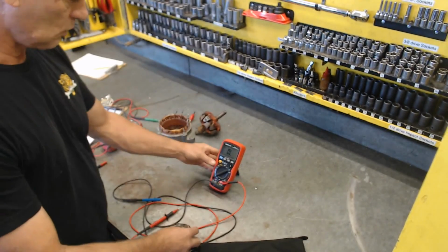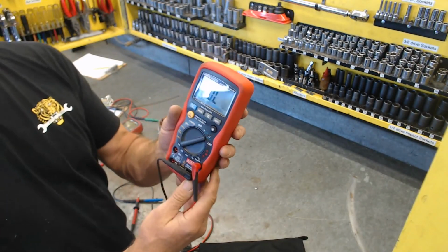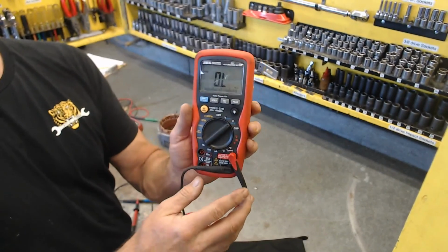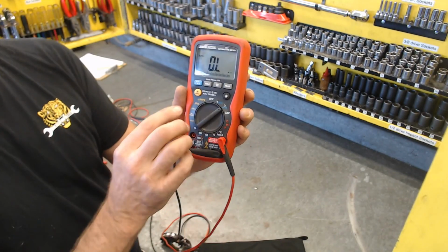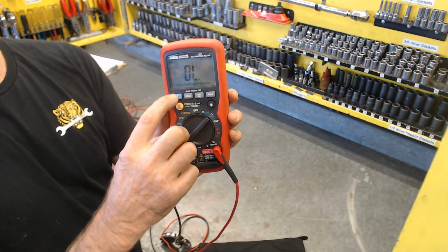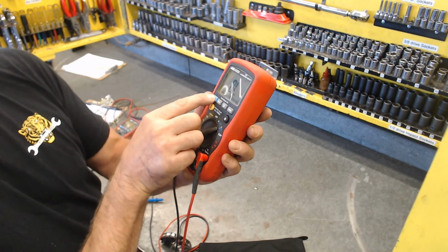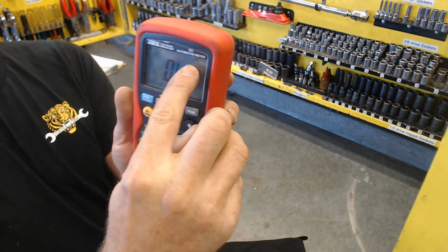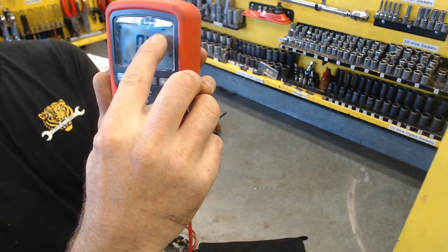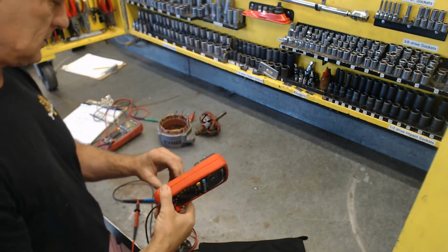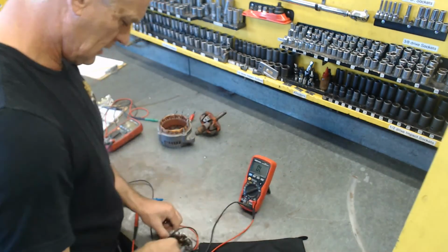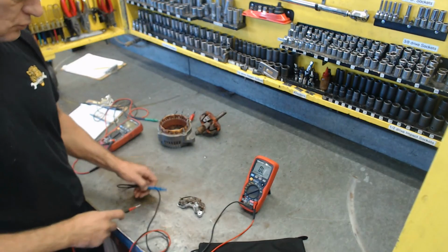the diodes. So what we do is we put this on the ohm setting here. See if I can get it so the glare is not so bad. And what we're going to do is we're going to push this, and we see a tone symbol. Push it one more time, and we see a diode symbol up there in the corner. So now we can check this for diode resistance. What it does is a voltage drop on this.